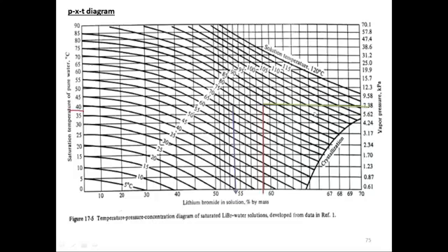So its vapor pressure on the right hand side will be 7.38. The vapor pressure is 7.38. So the other tank must have 7.38 pressure. So if 7.38 pressure is there, and we know the temperature, we can measure the temperature of the solution, and we measured it, it says 80 degrees centigrade. So we draw a horizontal line from 7.38 to this solution line. This is the solution line. This is the solution temperature. These are the different solution temperatures.